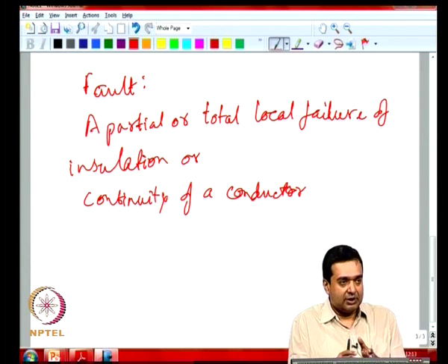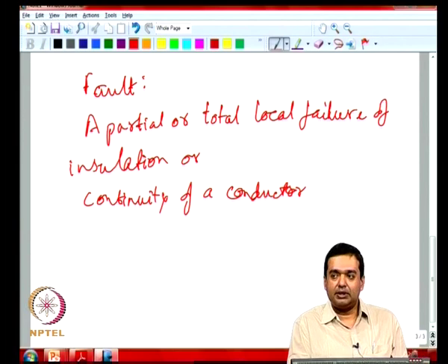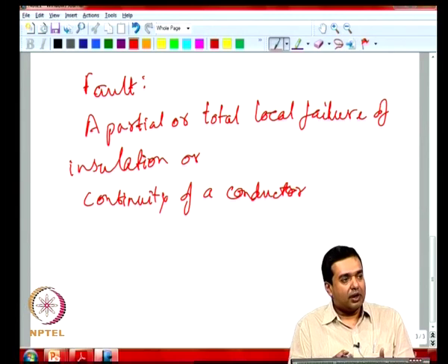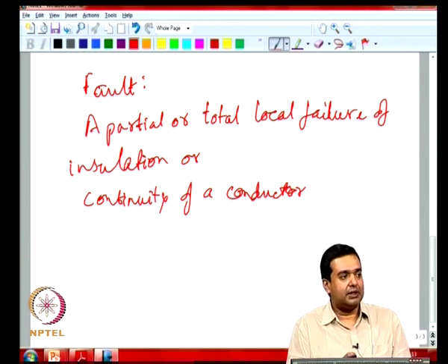So, maybe on a section of the feeder you would see over voltage, but on the adjacent feeders and further away on the feeder what you would actually see is under voltage. Okay. So, you will have to look at a combination of what can happen when you look at a fault event on a typical distribution feeder.